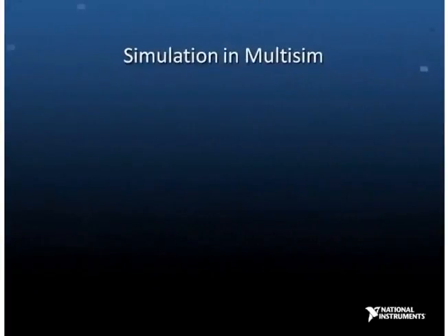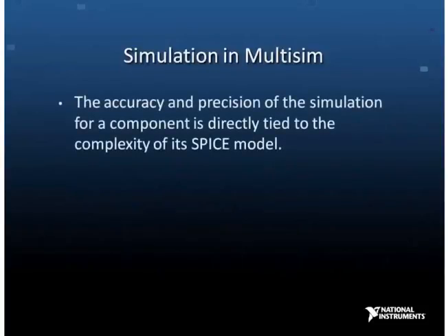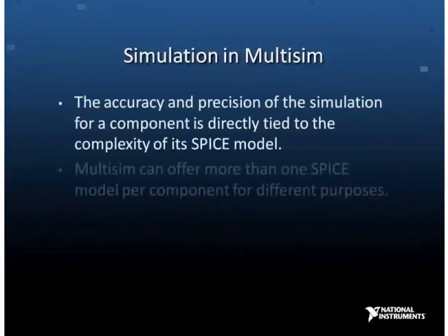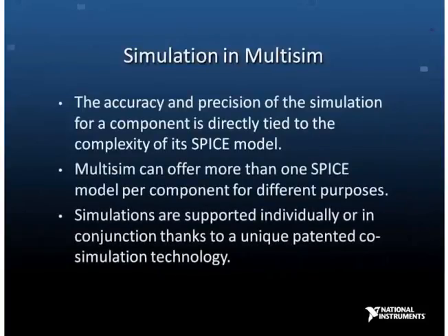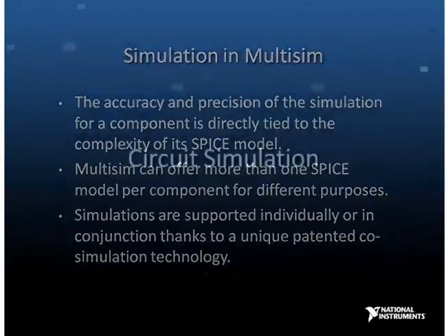Most components in Multisim have a model associated with them. Only green components in your schematic do not possess a SPICE model. They are merely placeholders. These components sometimes have more than one SPICE model. This is because they need to adapt the model to a specific simulation. For example, a less complex model might be ideal to simulate a transformer which handles high voltages, and high-precision simulation results are not needed for verification, whereas it is not the best choice for a highly restricted simulation environment where you're looking for exact results.